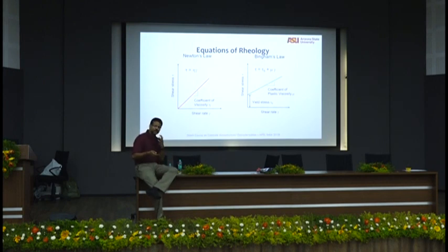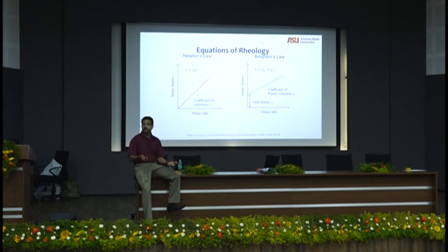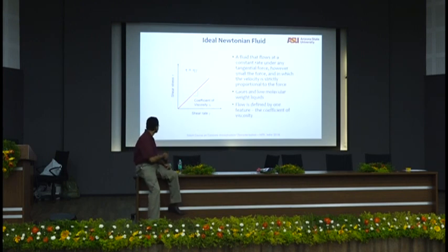So if you have a very dry concrete, you have to give it a lot of energy before it flows, and that lot of energy might not be used in flowing, it might be used in disintegrating the particles. Therefore, if you have a very low water cement ratio concrete or a very low slump concrete, more energy you give is detrimental because it's not flowing, it is just breaking apart. So you need to have the right material also for that to happen.